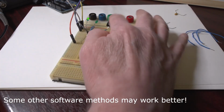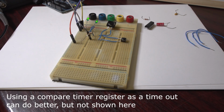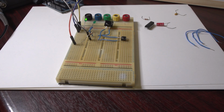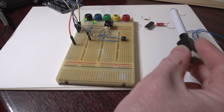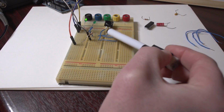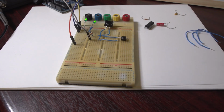Yeah, it's not bad at all, and you could probably get away with it for most projects, but you have to bear in mind it's not a complete solution, and that's why the hardware version is, in my opinion, actually better. You get much more reliable results with the hardware version, and it means you don't actually have to have those extra lines of code in the software. But if you were pushed from a money point of view, or even a space point of view on a PCB, and there was good reasons to remove the hardware, then this is another way of doing it. It's a complete software solution for the contact bounce problem.